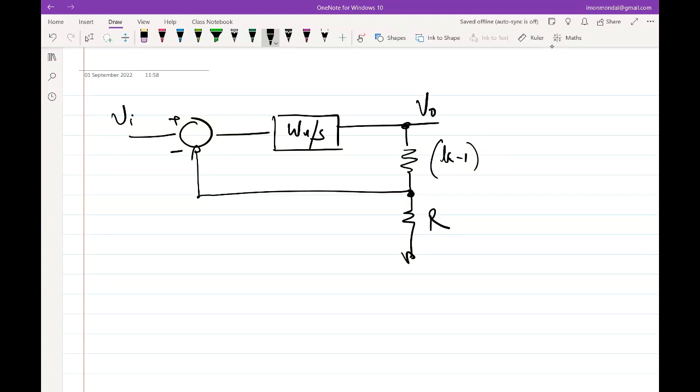Here we said, how do you figure out the loop gain? You can break it at any point and apply a test voltage, and see what the return voltage is, and then you do minus V return by V test. But that's not the full story.